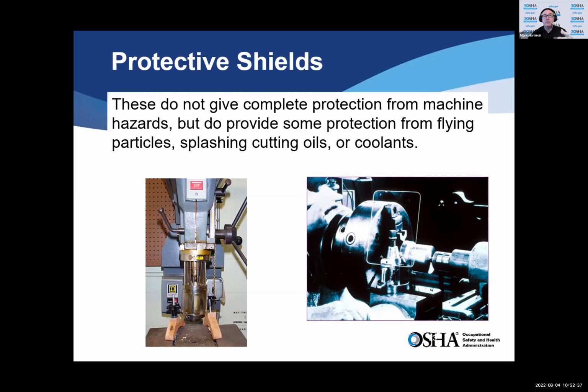The guard itself is sort of half-moon shaped. It usually is foldable, on a hinge, so it pulls up and goes down. You're protecting the worker from the chuck, which is rotating and not smooth. The little plexiglass shield there is just keeping the stuff that's coming off the part from hitting you. So that little shield is not really protecting you from the hazard of the rotating equipment.